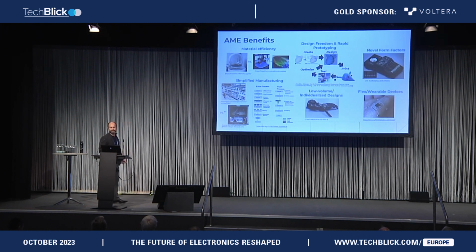So this brings us then to AME benefits and rationale for using AME for electronics manufacturing, highlighting the efficiency of depositing materials only where you need it compared to traditional methods which utilize areal deposition and then selective etching, as well as the design freedom that is gained, coupled with an ability to rapid prototype for fast learning cycles, enabling ideation, design, fabrication, testing of a device within significantly shorter timescales, from cycles of days or weeks for traditional processes to hours or even minutes within some AME processes. And then also novel form factors